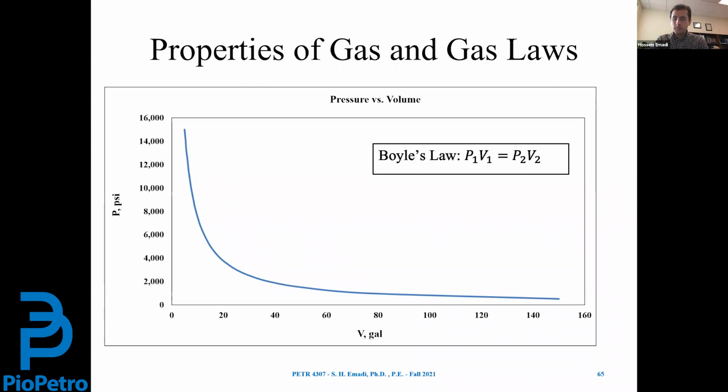So basically, it is very similar to the first circulation of the driller's method. However, it is not a continuous circulation. It's basically an intermittent approach. So we let the gas expand and then remove the mud, and then expand, remove the mud volume. I'll talk about the exact calculation in a future slide.